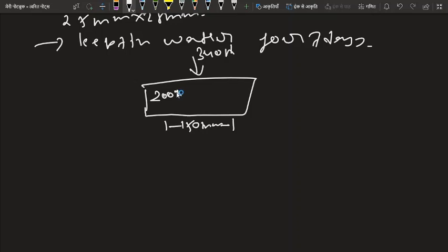After 7 days the specimen is placed on two supports spaced 150 mm apart. A load of 340 Newton is applied on the middle of this specimen, which is called a point load or concentrated load. The specimen should not show any sign of failure.